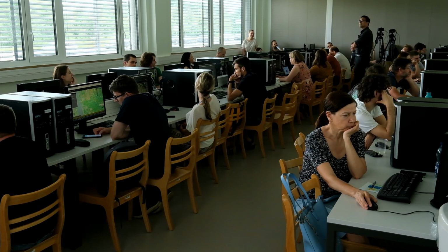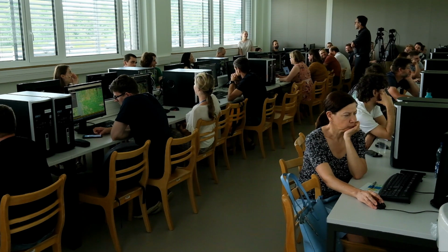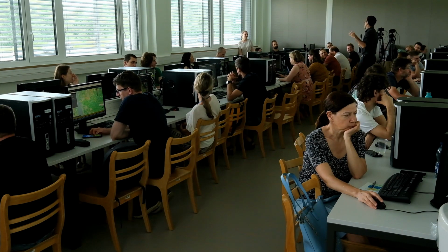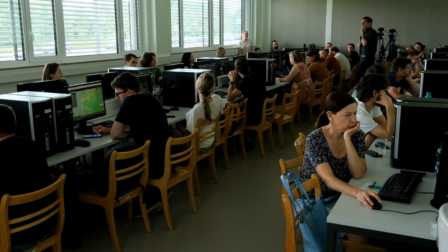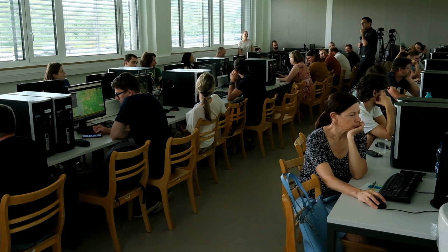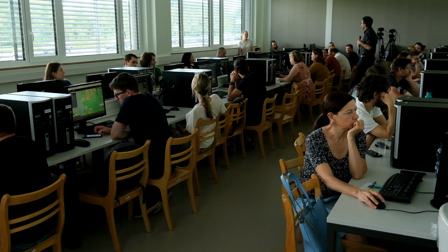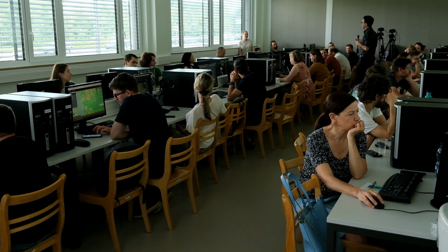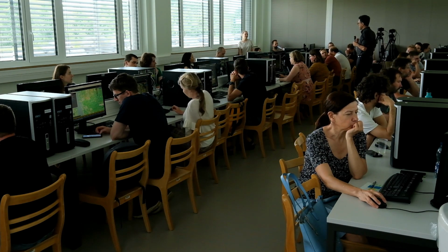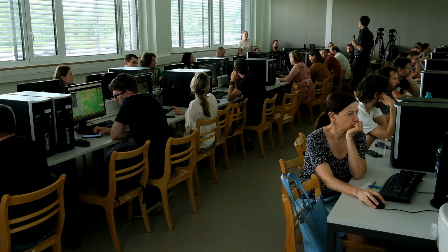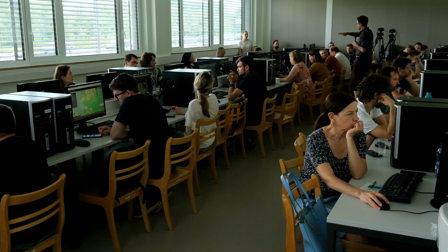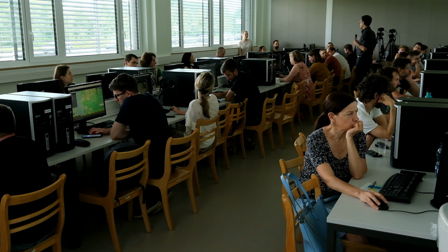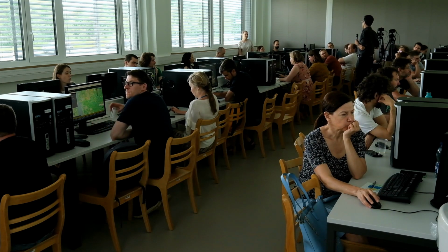Good question. Well, if you go to very big areas, you can look at this Copernicus map that I showed you in the beginning for the whole of Europe. For the really big signals, you need to combine it with different techniques, mostly because of the drifts that we can still have in the data. If you have long time series over long spatial ranges, we have trends, for example due to the troposphere or the ionosphere.